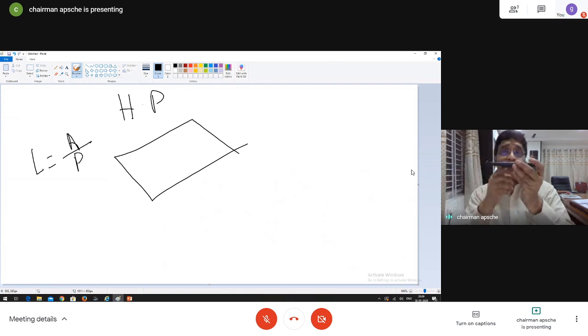The same can be explained on the bottom surface. Bottom surface. What is it? When the bottom surface is hot, all the molecules coming here come in contact with the bottom surface. It is already hot, and therefore they acquire the temperature, lose their density. They would like to go up, but the plate is restricted. The plate is the boundary, and therefore they cannot go further. So all the heated molecules stay at the plate. So a colder molecule will not get an opportunity to come in contact. That is unfavorable. Meaning what? A horizontal plate with the top surface hot is very good.